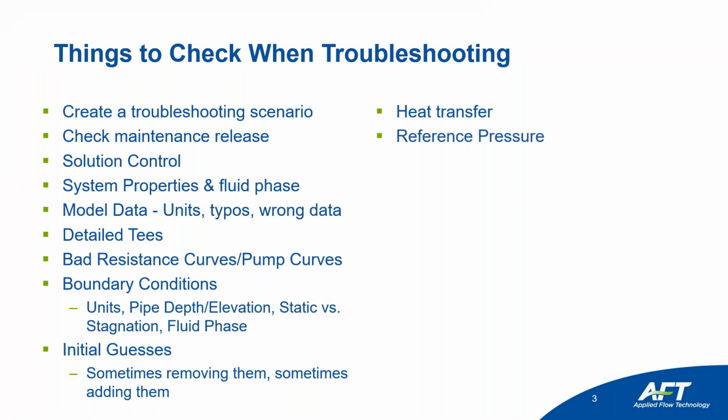Another thing I check for is reference pressure issues. Well, this is not really something I check for. It's more something that users will typically run into. Essentially, if you have a fixed flow at one point in your model and another point in series where there's another fixed flow rate, it's possible to calculate a dP that will drive that flow.